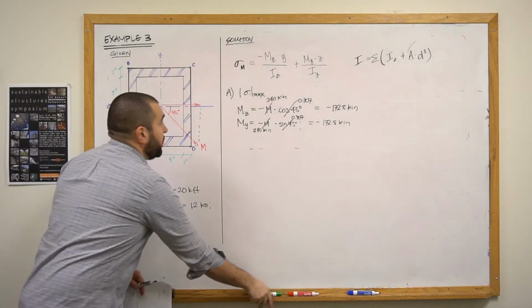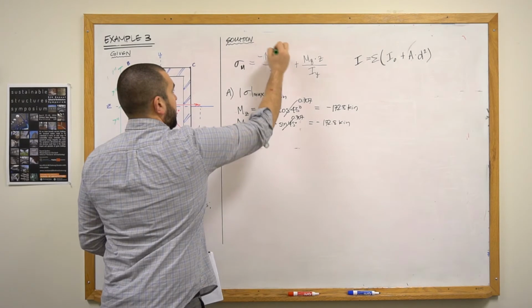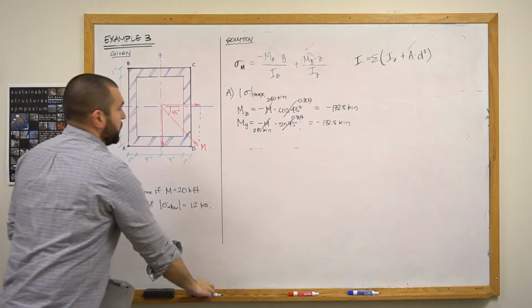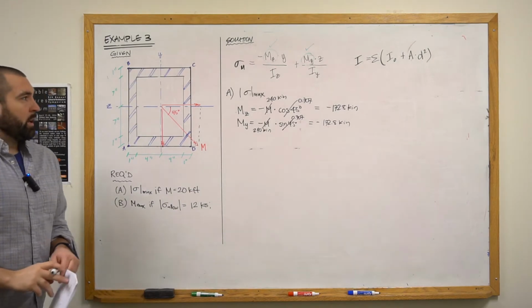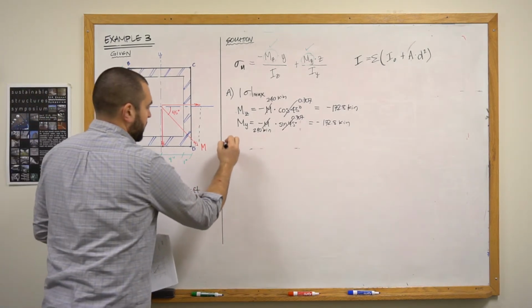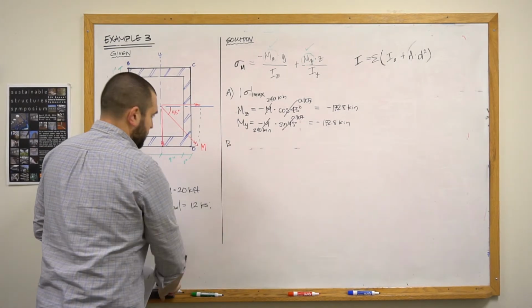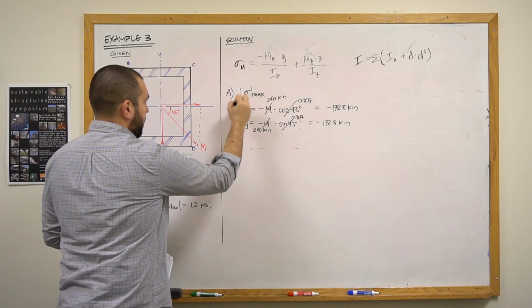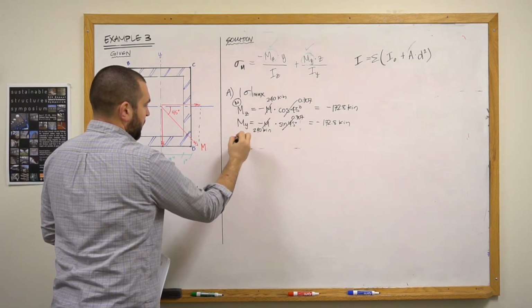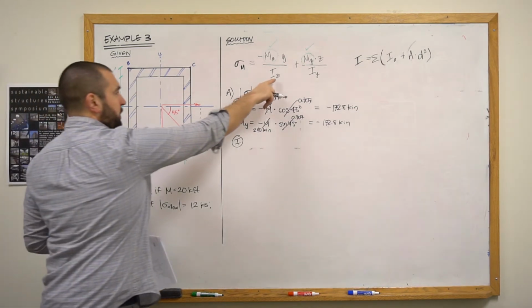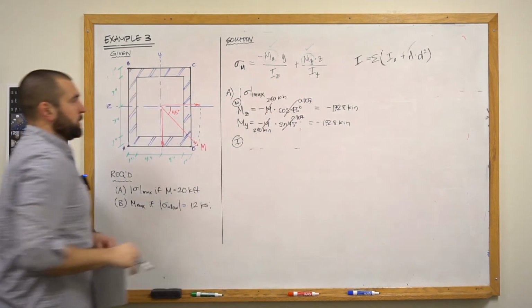Okay, so at this point we've got Mz calculated, we've got My calculated, which is great. So then next step, again, any order will be fine. We're going to look, sorry, not part B quite yet. So here we calculated M. Now I'm going to calculate I. And so we need to calculate both the moment of inertia about the z-axis and the moment of inertia about the y-axis.